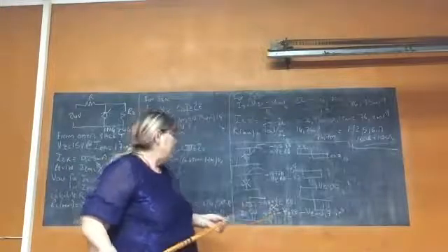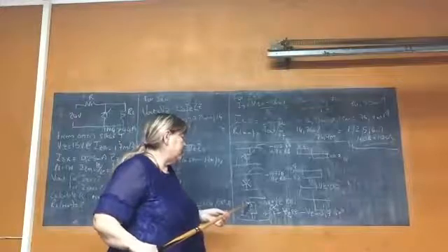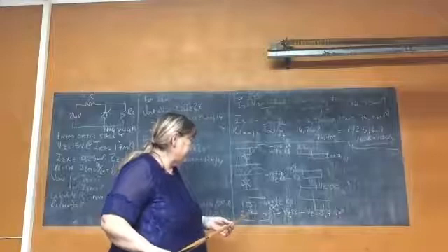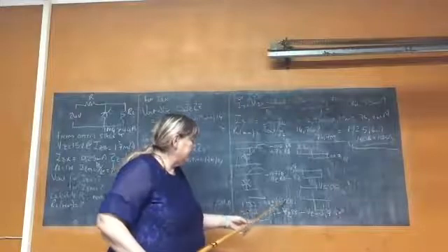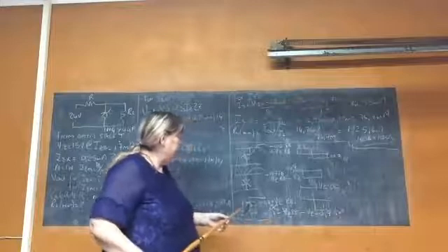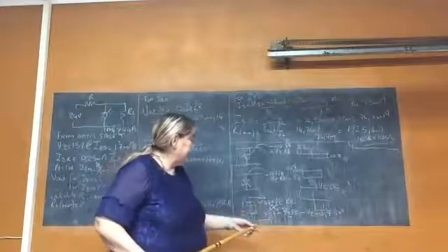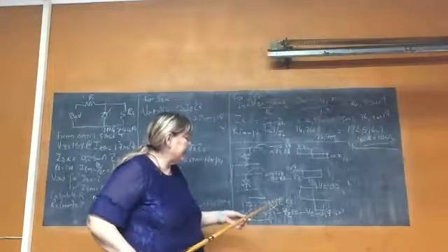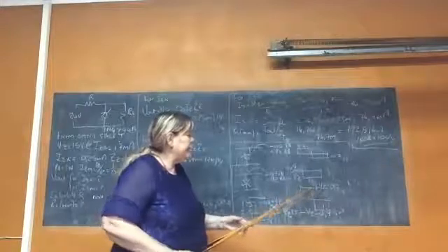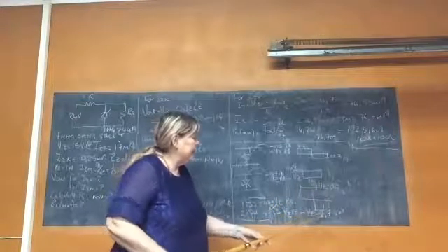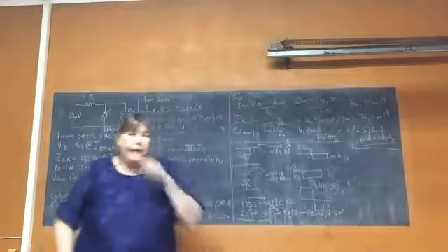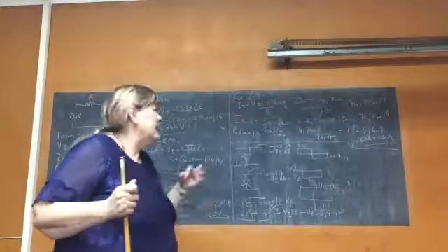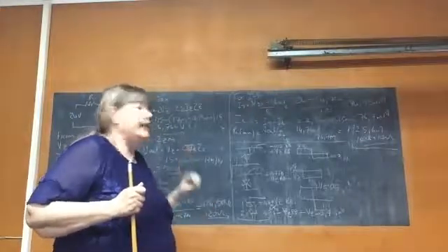If you know, this diode will give me minus 0.7 plus Vz, plus 0.7 minus Vz. You can do your cross connection and your output will be minus 0.7, minus Vz and plus Vz, plus 0.7. And you can draw it. Plus Vz, plus 0.7, minus Vz, minus 0.7. And that is the easiest way to remember clipping for Zener diodes.